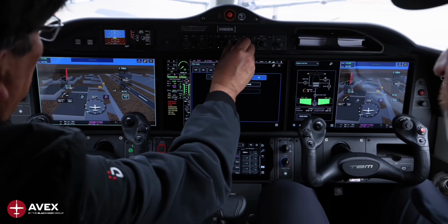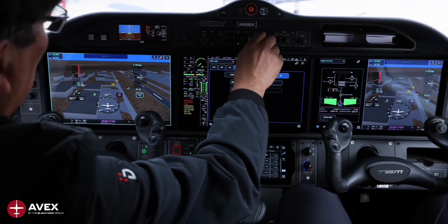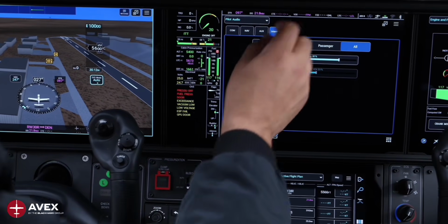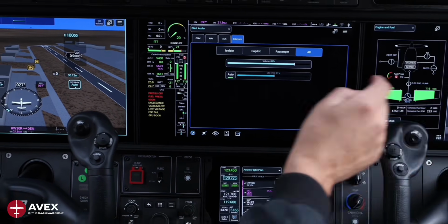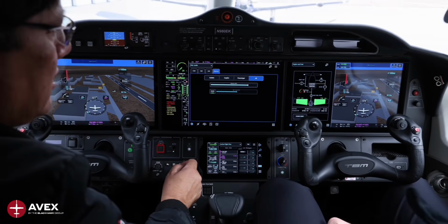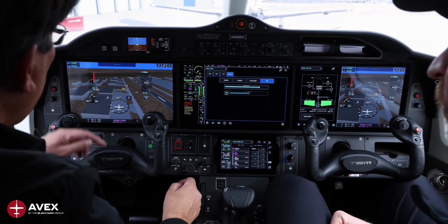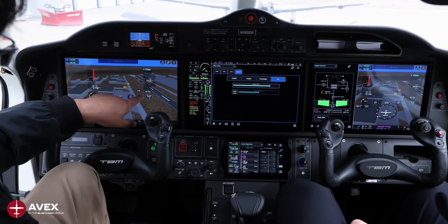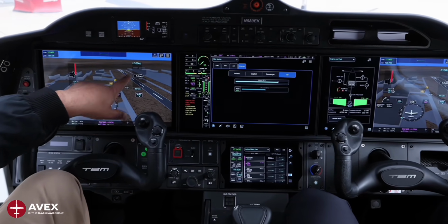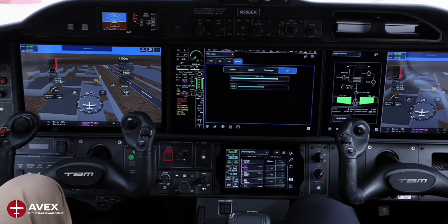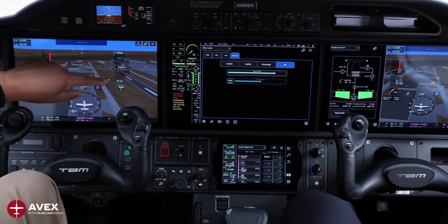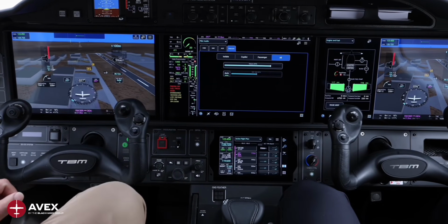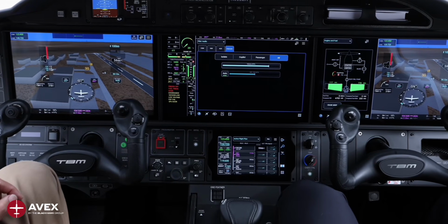That altitude is up here. Okay. Yeah, that's for certification. They want it to be common to the pilots. But underneath that, the altitude pre-selector, the barometer you can select. Everything that has a rounded bevel, you can select. If it's sharp, then it's non-selectable. That's why you see this sharp, non-selectable. But the auto, rounded bevel edges, we can select. So that makes it easy to know.